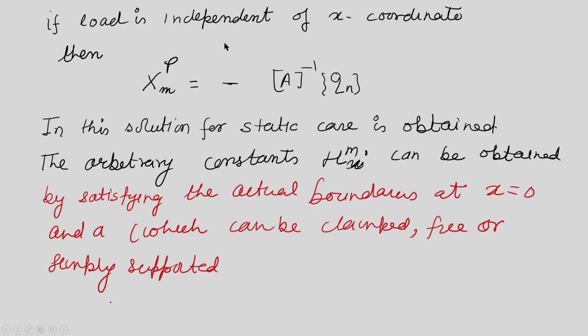Now, if we say that the load is independent of the x coordinate, in that case the particular solution can be written like this. In this way we can get the solution for a static case, and the arbitrary constants Hm can be obtained by satisfying the actual boundary conditions at x equal to 0 and x equal to a, which may be clamped, free, or simply supported. In this way, the displacement based Levy type solution is presented.